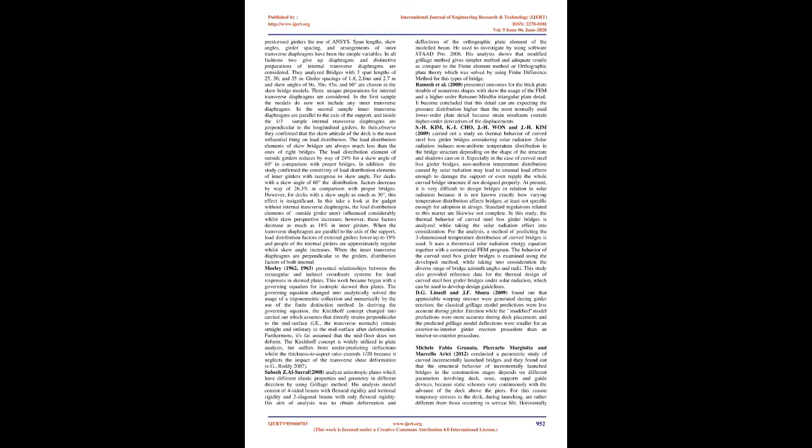Morley, 1962, 1963, presented relationships between the rectangular and oblique coordinate systems for load responses in skewed plates. This work began with a governing equation for isotropic skewed thin plates. The governing equation was analytically solved using a trigonometric series and numerically by means of the finite difference method.